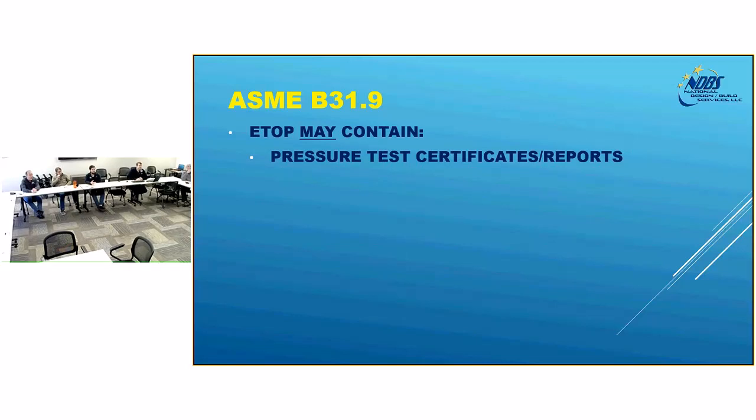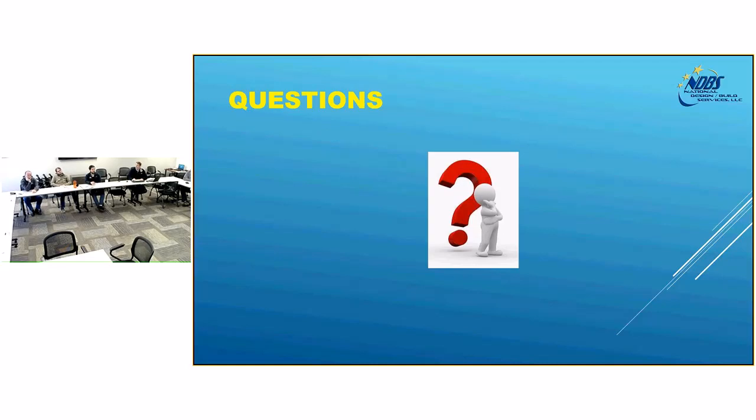You may end up with some pressure test certs on your B31.9 systems. Sometimes they make it in, sometimes they don't. It's not a code requirement for B31.9. So that's all I've got.